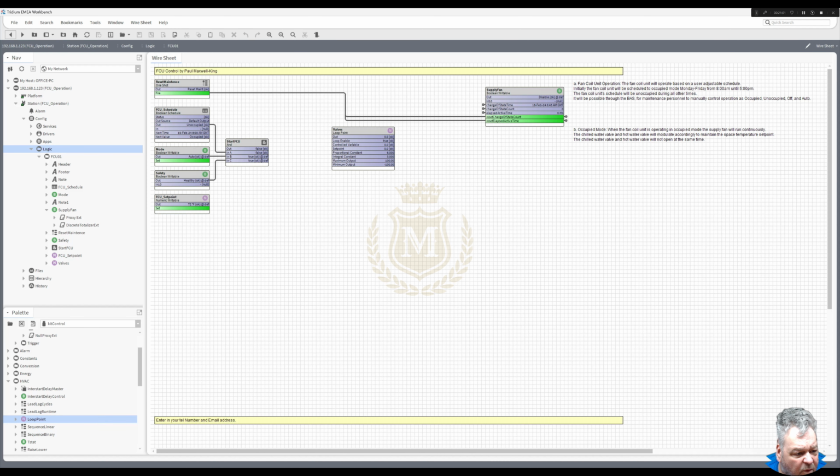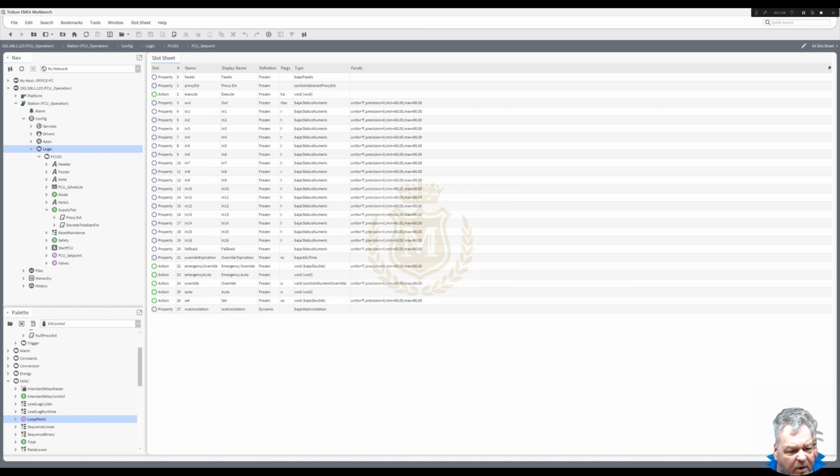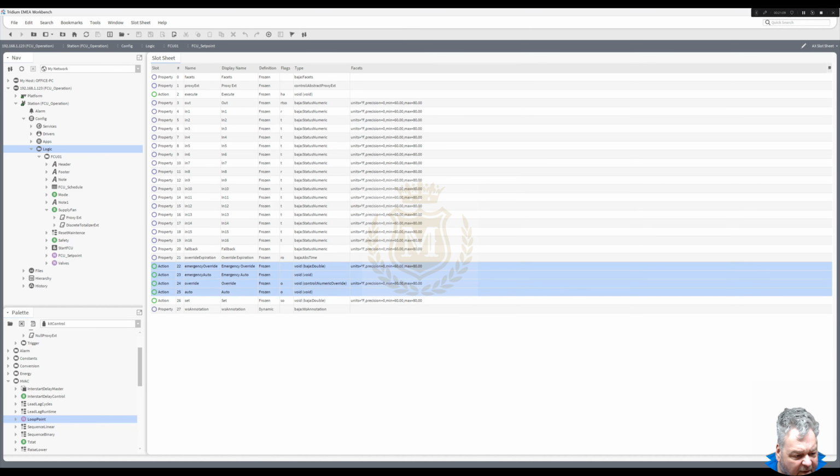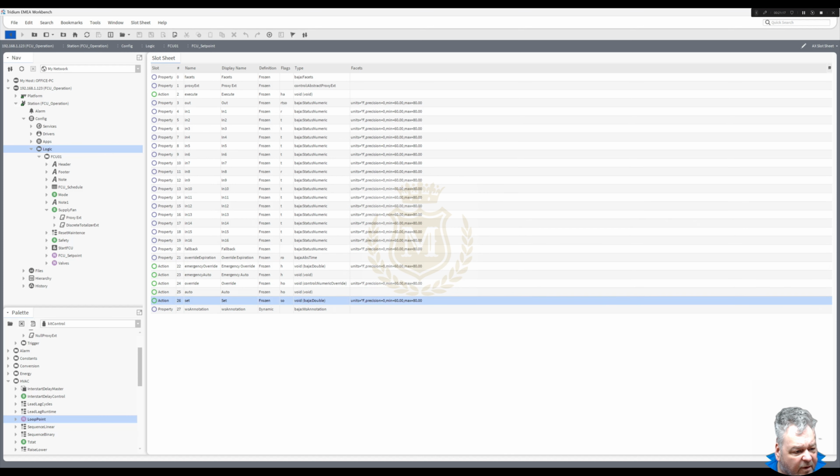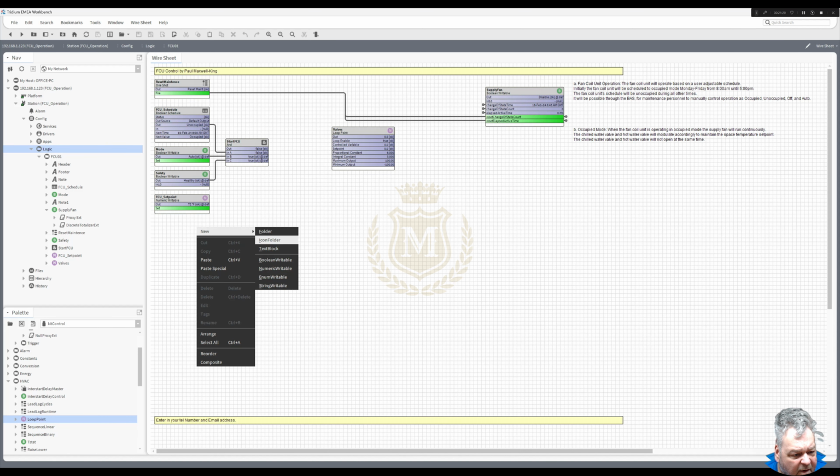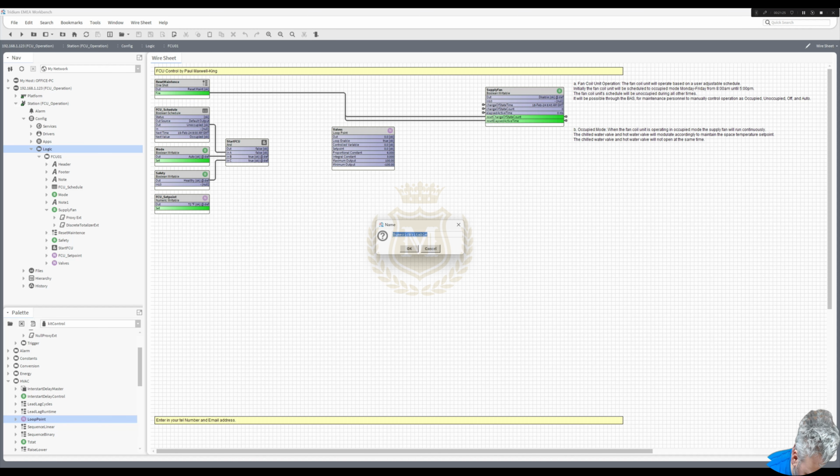So in order for that to work, we definitely will need a temperature. Let's just check that we hide everything to do with other objects we want. So we've just got the set point there, and then let's go to another numeric writable, FCU room temp or return or whatever it's going to be, but that is going to be our control variable for our fan coil unit.